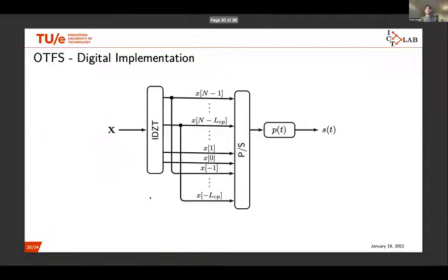And when we talk, then we can also model our OTFS modulation in that way by saying, okay, instead of modulating or transforming all the symbols from the delay Doppler domain to the time frequency domain, we can directly apply the inverse discrete Zak transform on our matrix X in the delay Doppler domain. We get a sequence in the time domain, and similar to OFDM, we want to have cyclic properties, so we add a cyclic prefix. And then we do the parallel to serial conversion, and we transmit the pulse amplitude modulation, and we transmit the signal.